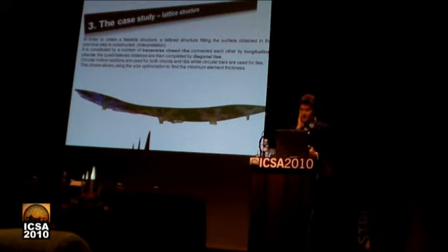And in this sense, we create a latticed structure. This latticed structure is composed of 4 pillars. So we have 4 assemblies: first assembly, second assembly, third and fourth. Each one of these 4 assemblies is made by 3 different components. So we have transverse closed ribs, longitudinal chords, and diagonal ties.